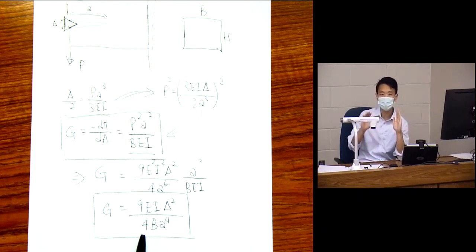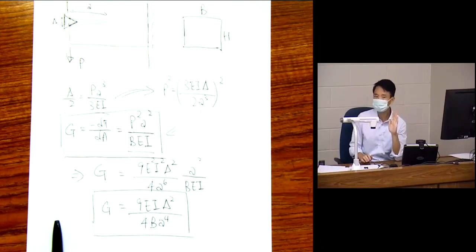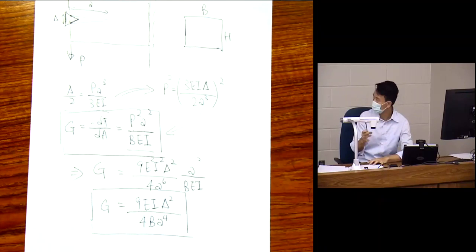First of all, as I'm loading this with the wedge, I'm going to start growing the crack once G equals gamma. Now gamma stays constant with A. Now A grows slightly. G reduces. That means now G is smaller than gamma, right? And so the crack stops because the fracture energy is no longer satisfied, right? So I'll formalize all that again in a minute, but just by looking at this result, we can get a lot of physical insights and then just explain this to you.